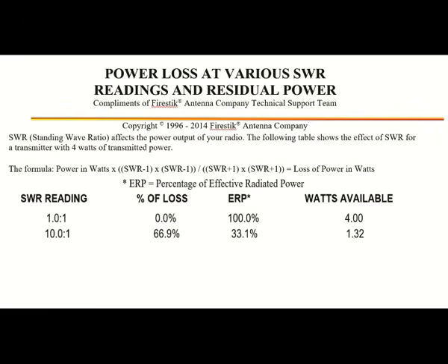So we're going to focus on a 1-to-1 SWR reading on the 25 feet of LMR 400 at the load into that transmission line, and then we're going to focus on changing that to a 10-to-1 SWR at the operating frequency by adding a reactance and modifying the impedance a little bit, to make it a 10-to-1 SWR.